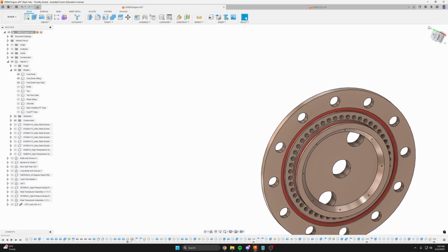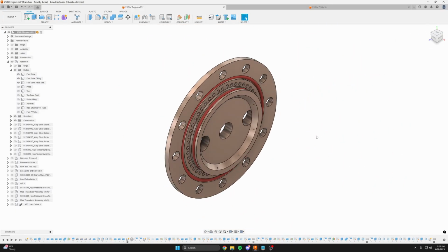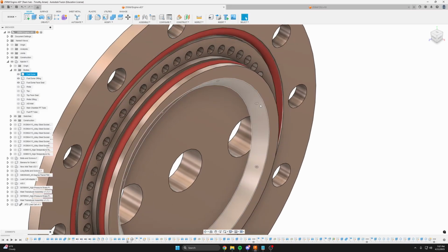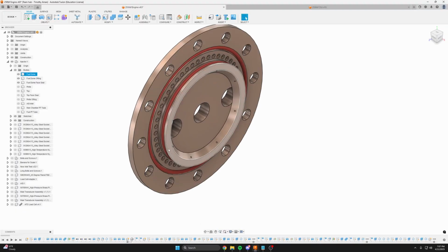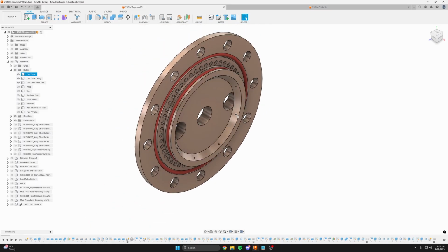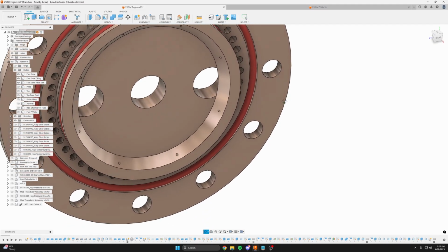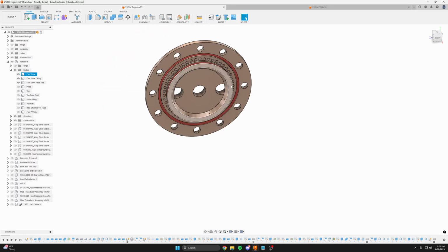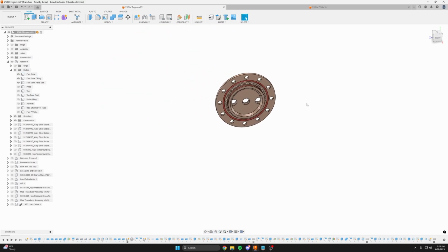I will put the caveat that we have not fired this engine yet, so I do not know how effective these film cooling holes will end up being. There aren't that many of them. Ideally you'd have as close to a perfect sheet around the wall as possible. So the space in between these holes may make them not as effective as we'd hope, and also they're not perfectly on the chamber wall. But that's just another thing to consider.